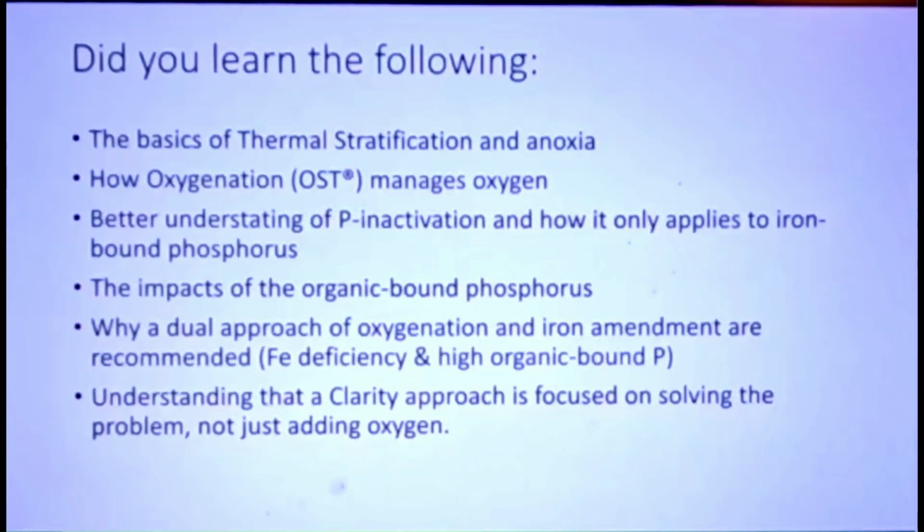So really quick, before I get into the next slide, I'm hoping that you're able to take away so far the basics of thermal stratification and anoxia, how OST manages oxygen, a little bit better understanding of phosphorus inactivation and how it only applies to iron-bound phosphorus, the impacts of organic-bound phosphorus and how it's the wild card, and why a dual approach of oxygenation and iron amendment is recommended, specifically because Lake Lawrence has an iron deficiency and it has a high organic bound fraction.